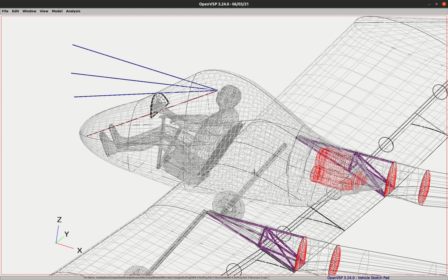So at least for this initial design, I think I'd rather go with a steel truss fuselage and then cover it with a really thin shell of some kind of composite. I don't mind if the shell fractures, because if I design this right, the steel truss fuselage should keep those sharp ends from coming in and impaling the pilot.